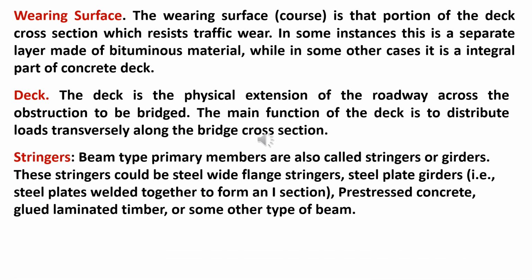For the stringers, beam-type primary members are also called stringers or girders. The stringers could be steel wide flange stringers, steel plate girders, in other words, steel plates welded together to form an I section, prestressed concrete, glued laminated timber, or some other type of beam.